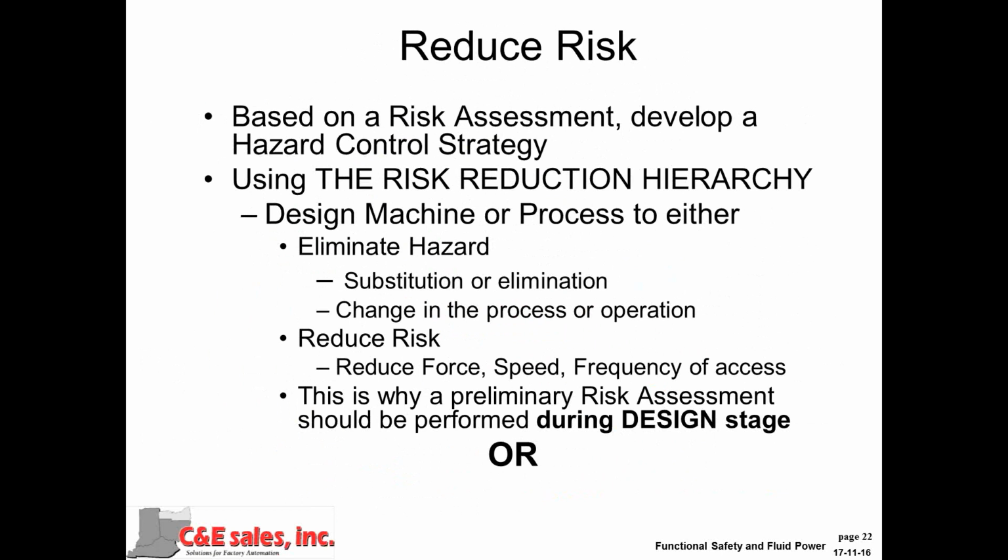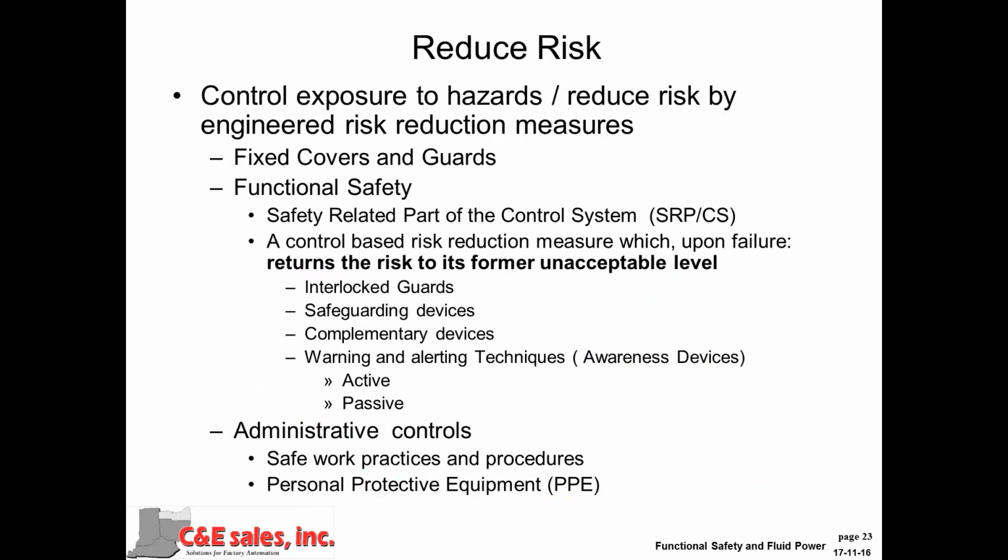It is important that this risk assessment be done during the design phase, if at all possible, because this is where you have the most opportunity to affect a positive change. If the design modifications don't get you where you need to go, then we go to what we call engineered risk reduction measures. These are typically fixed covers and guards, or such items as a related control system, what we call safety-related parts of the control system, where we use